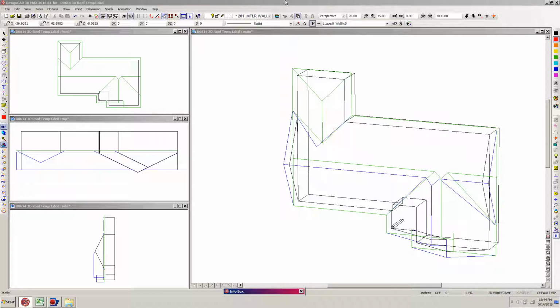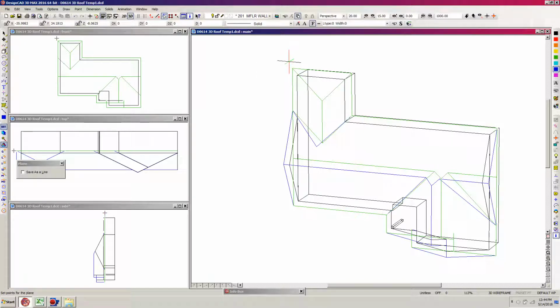And so what I'm going to do right now is hit B for vector, or I'll just hit P for plane. Might as well just do the plane, but I want to get into blue, which is our color we're using for our roof. I'm hitting P for plane. I'm going to right click here, and then right click here to this corner, and then here I'm just going to gravity move, and because it's going to be flat, you'll see it here in the Z distance, that when I gravity move using the comma, it's a 0.